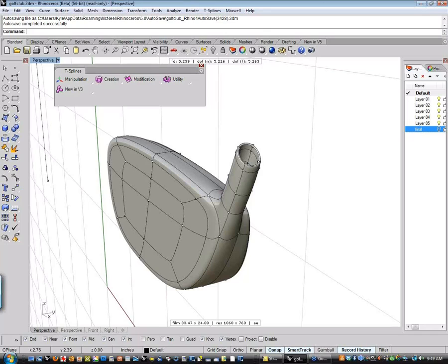This command that we call TS match, or the match command, is something that we actually just barely completely rewrote to make it a more robust command. But what it will let you do is match any border T-Splines edge with a NURBS curve, a NURBS surface, a trim NURBS to really aid in getting those transitions from the organic T-Splines geometry to something more exact. So yeah, I'm interested to see how it works in this instance. But okay. Uh-oh, I may have killed it.